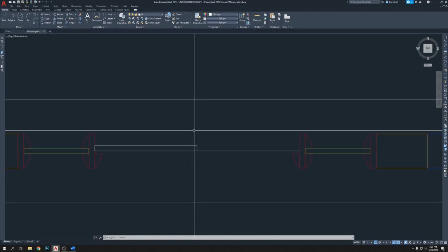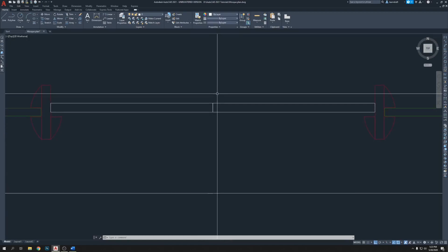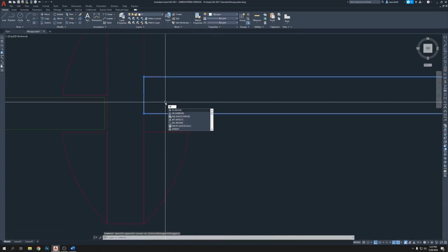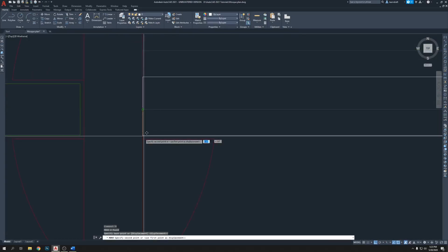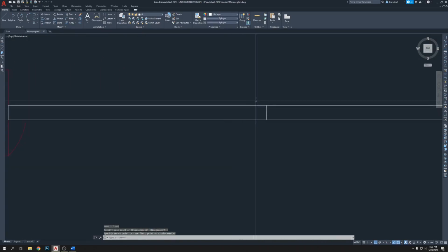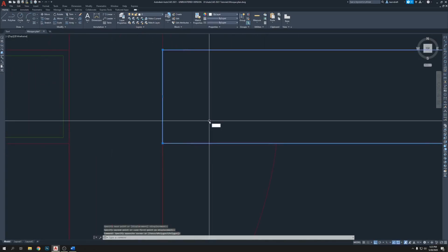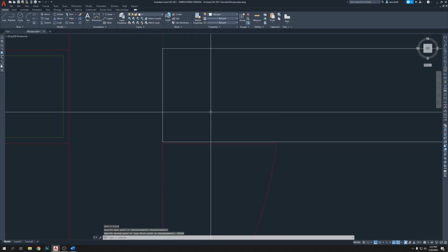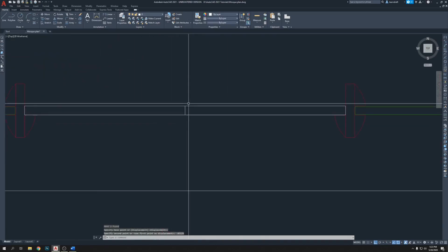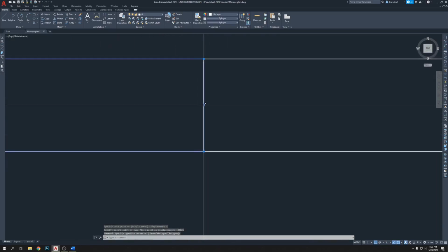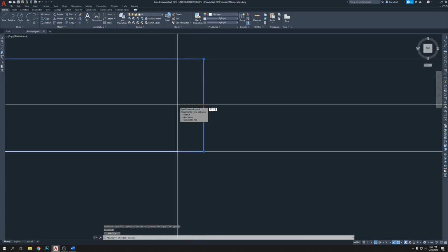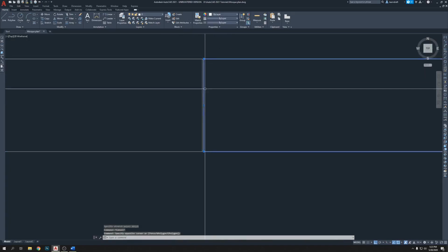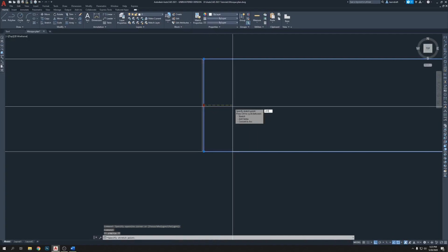Okay. We are going to work on the main door now. So let's bring it a little closer. It's just too far. Select both of them. Move from here to there. And I'm going to make some space, maybe 1/16. Move 0.03125. And the gap is going to go both ways, 0.03125. Enter. 0.03125.